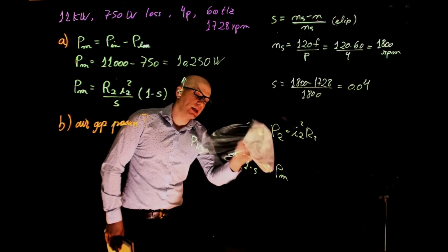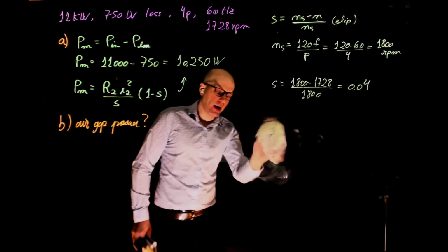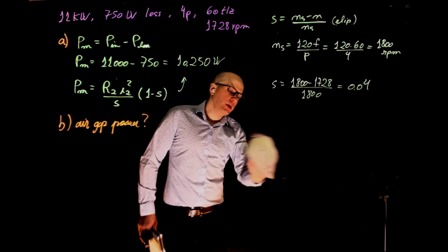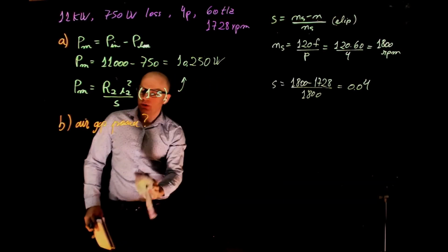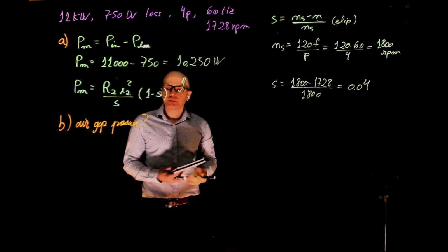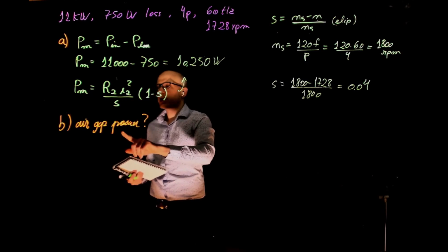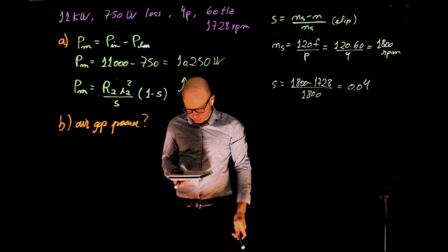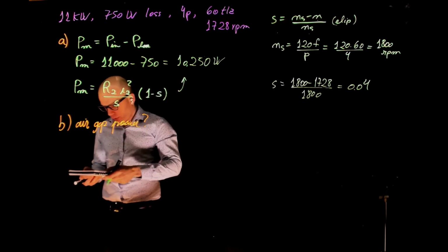That's actually a good mistake to make, because now we can establish one more time the power flow. So don't worry about that. Okay, so what is the air gap power? How do you relate the air gap power and that? Is it just PM over 1 minus S? PM over 1 minus S, exactly.